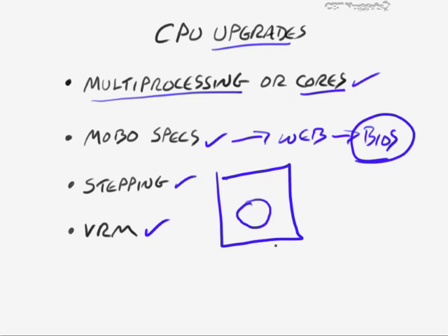Now, some heat sinks have this thermal paste already on them. It's kind of pre-packaged and pre-manufactured at the company. That's the case with my liquid cooled solution that I showed you earlier. It had some thermal grease on the bottom of it already, so I didn't have to be careful about how much of this to gauge. But if you do eyeball it, then you just have to be careful with it.